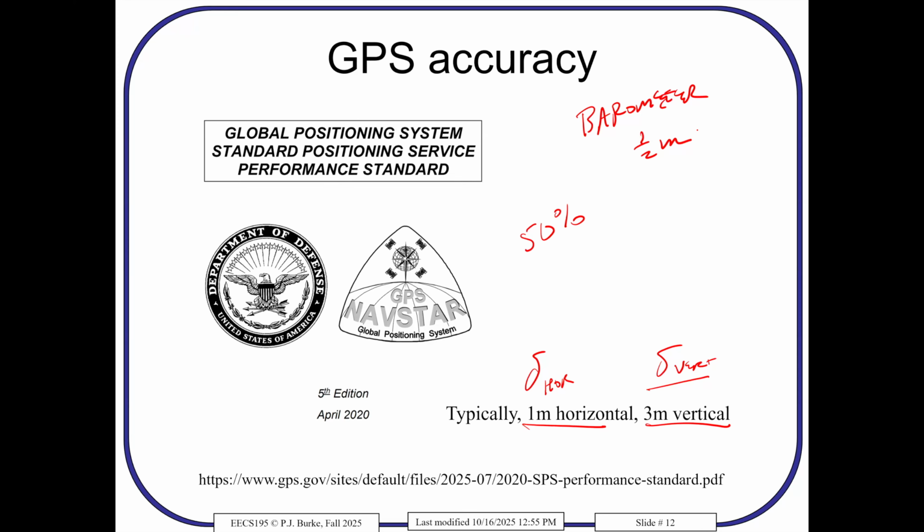So what I'm going to have you do is fly completely manually in the drone cage. I want you to control the throttle, and I want you to control the horizontal position. I want you to learn how to do it the old-fashioned way with no navigational aids. The only aid you have is auto leveling, and practice that. You don't have to be perfect at it, but please practice that. Because then when all these autonomous systems come in, you'll appreciate them all the more.